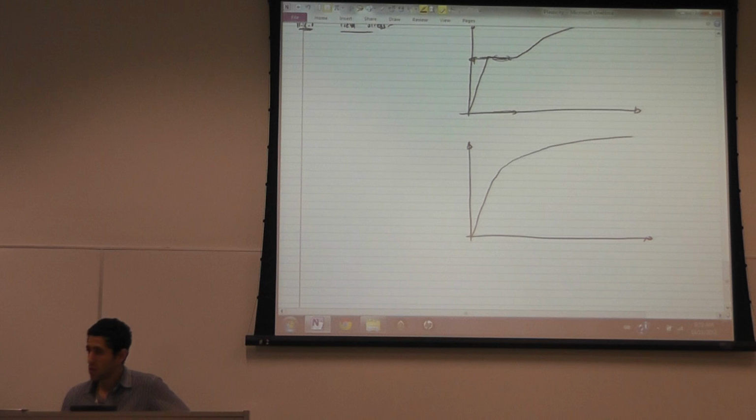Traditional steel codes adopt the 0.2% offset. If you want to find your yield stress, take an offset 0.2%, and draw a straight line, and where it intersects, call this your yield stress of that particular material.